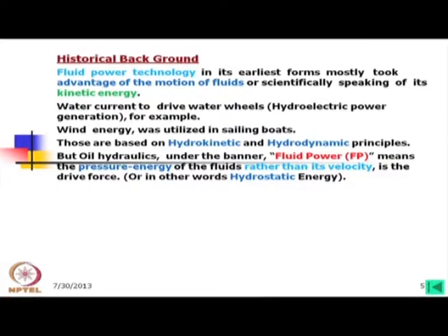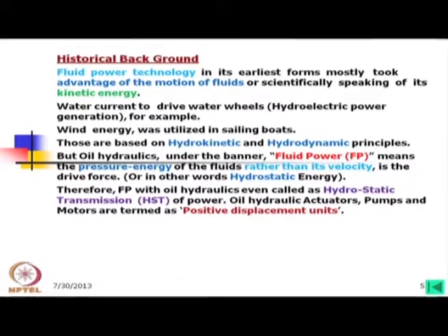But oil hydraulics under the banner fluid power means the pressure energy of the fluid rather than its velocity is the drive force. Or in other words we would say that we are using hydrostatic energy in case of fluid power. Therefore, fluid power with oil hydraulics, even called hydrostatic transmission of power, in short form we call it HST system. Oil hydraulic actuators, pumps and motors are termed as positive displacement units.